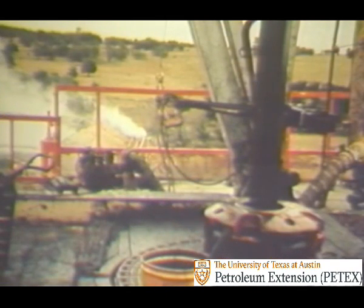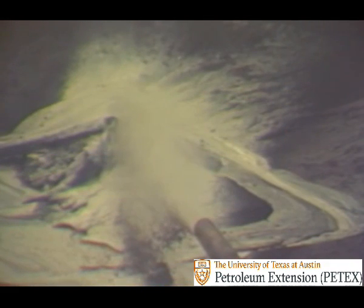But not all drilling fluids are liquid. Note the dust in the background at left. The dust shows that air or gas is being used as a drilling fluid on this rig. Here, a drilling fluid that is a combination of liquid and gas, mist, is coming out a rig's bluey line. Other gaseous mixtures include foam and aerated muds.